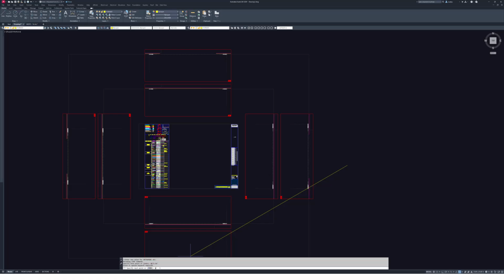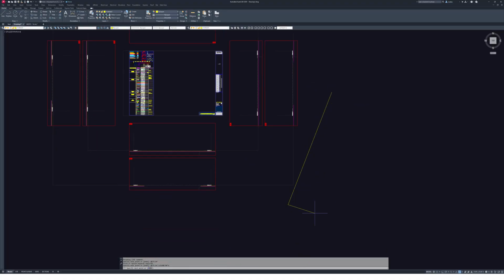So we're going to try it again, at 173.64 feet, and then caret, which is shift and the key above the comma, so shift comma gives you our caret. And we want to say south 21 degrees, 0 minutes, 0 seconds west. So you can see I typed all that in right there, and then we'll hit enter, and that gave us the line.